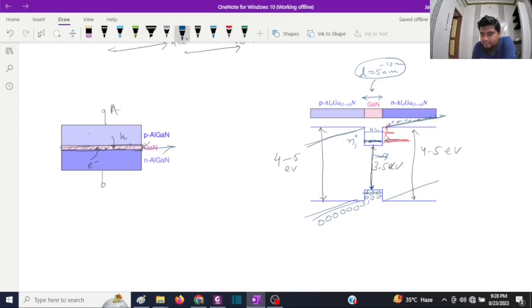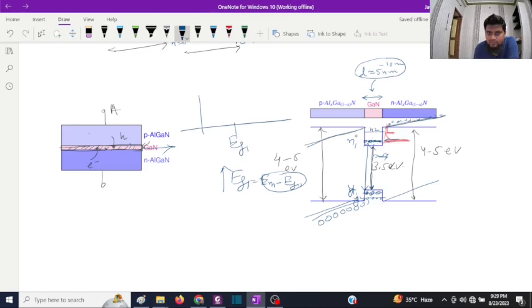Likewise, in the valence band, you will not have continuous holes, but they will be at, let's say, n1 and n2, like this. So the transition corresponding to this Eg1 varies from n1 to, let's assume, y1 and y2, corresponding to En1 minus Ey1, which is quite large, and you will get a spectrum corresponding to Eg1.